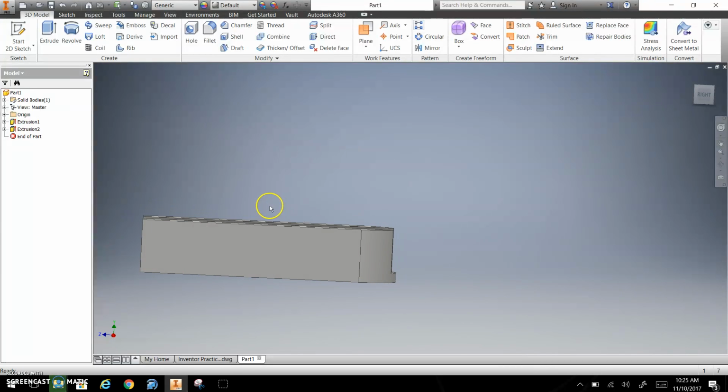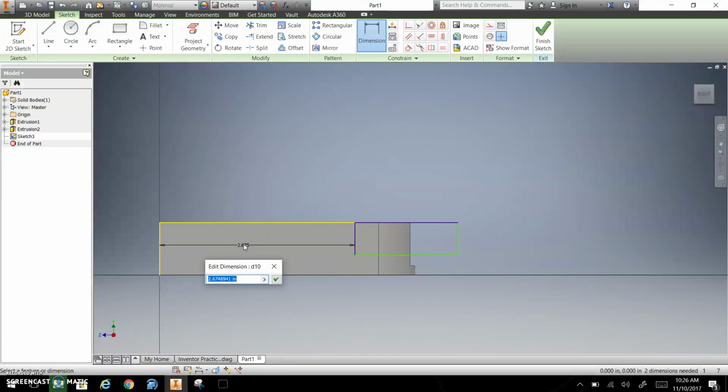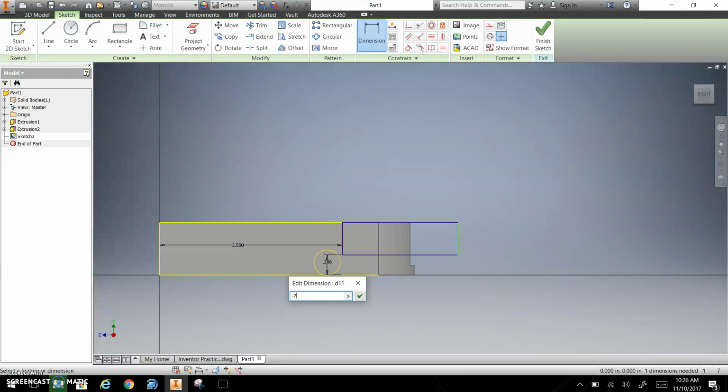The next thing I'm going to do, and I wish I had done this first, but that's okay, is put this cut that goes across the front here. And this rectangle, you're going to cut it, so it doesn't matter how far out this way you go. But this cut is 2.5 inches away. And then from the bottom, it is, let's see, 0.25. If any of these dimensions differ from the drawing, just go with what I do in the video and you'll be fine. It'll be close enough.